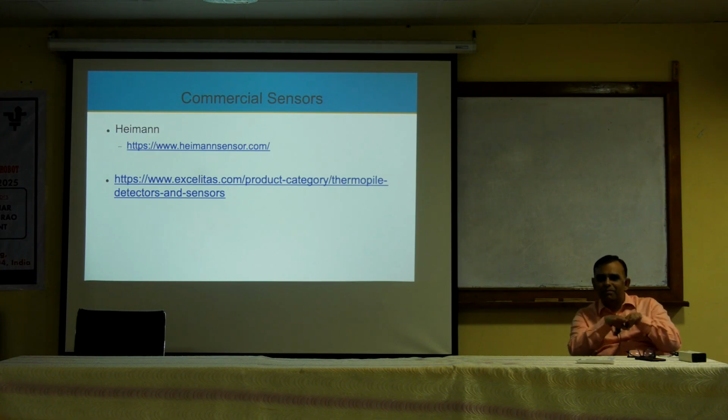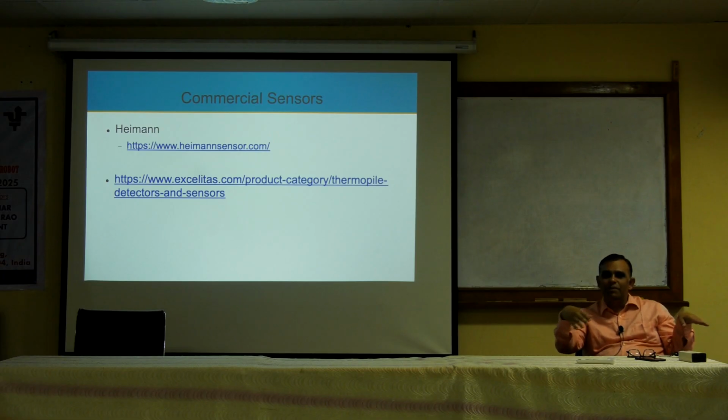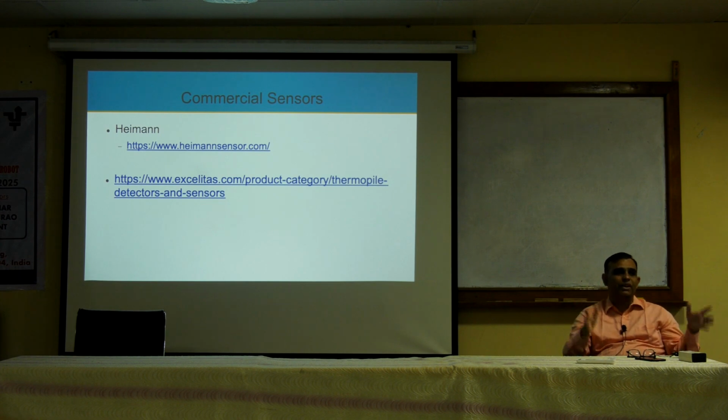In classic diode sensors, all the diodes were open, they were just receiving light. If my cold junction also gets hot, that will not be nice. So quite often such sensors are made with one sensor on a chip. You are essentially looking at just the amount of heat, not a particular radiation; you are not trying to take a heat map, you are trying to measure heat overall in the room.